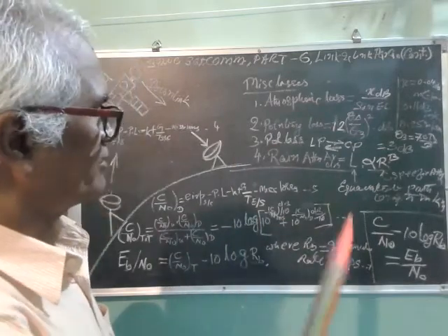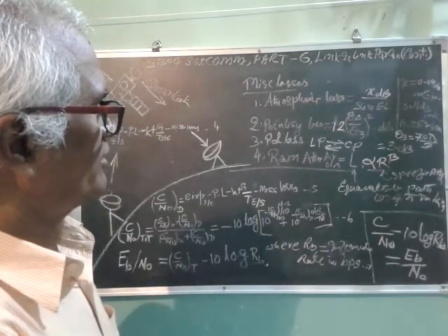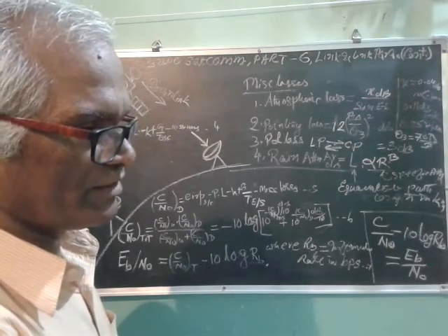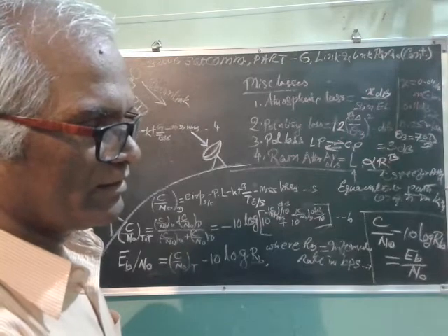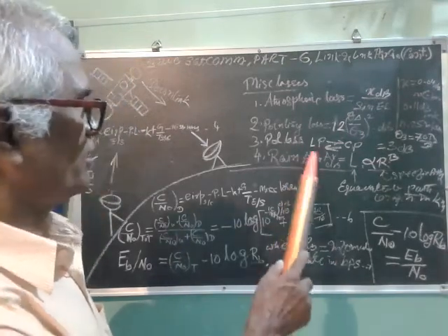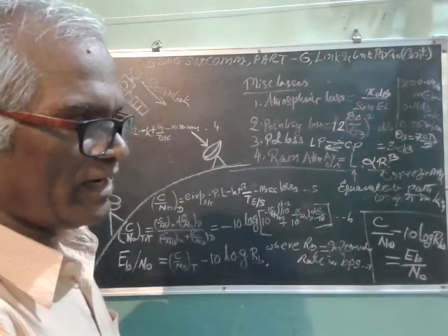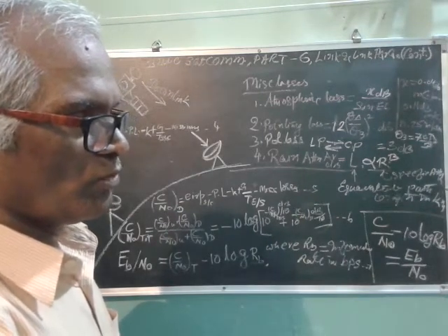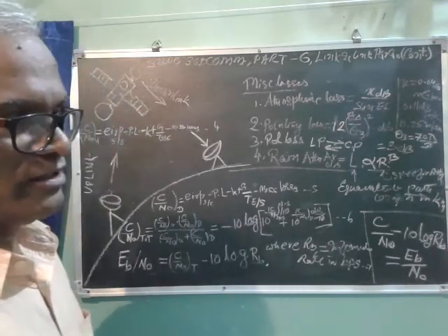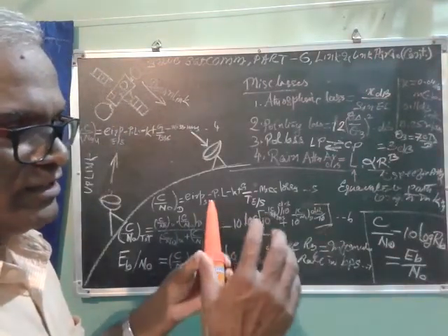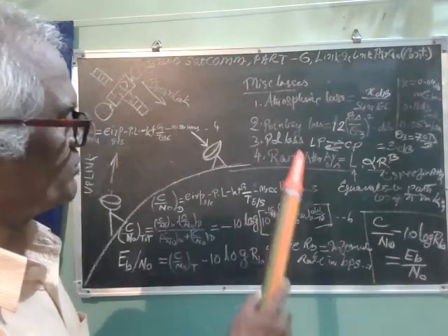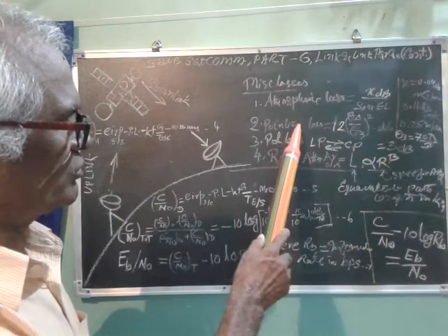But in some cases, like very low band operation such as telemetry, tracking and commanding, the satellite will have circular polarization, and it has another benefit also. Linear polarization has to be optimized by physical movement of the antenna. That's why mismatched polarization will be used.